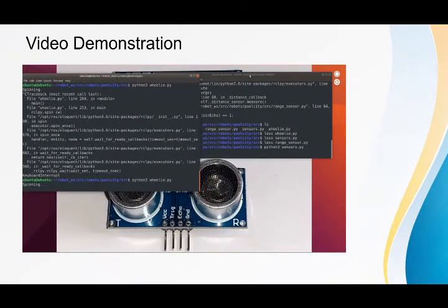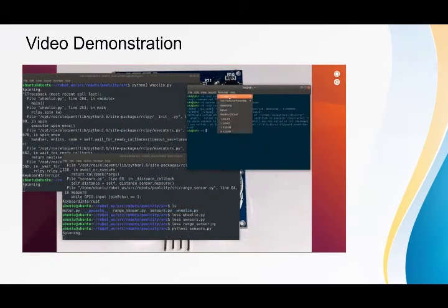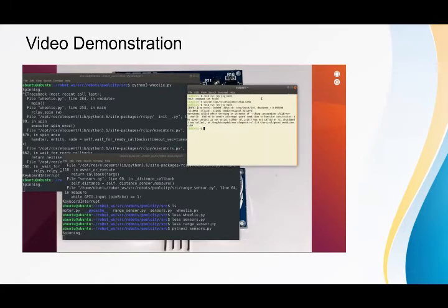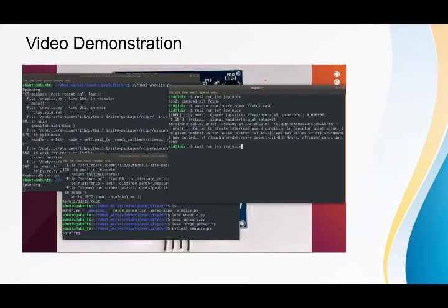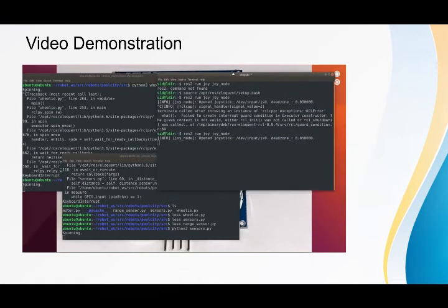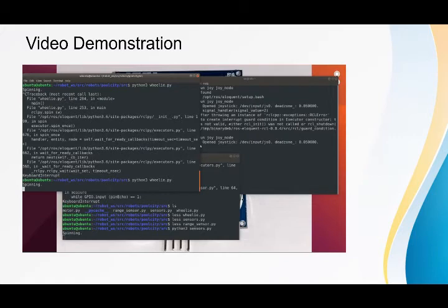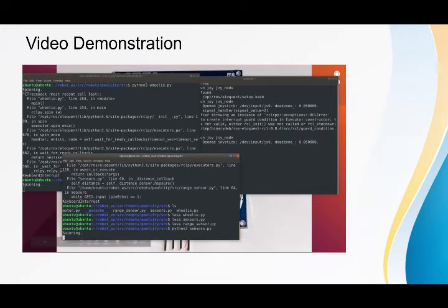The robot's going to be listening on that sensor topic to find out how far away it is, and then I'm going to run my Joy node once again on my laptop. Okay, so everything's all put together. I have 3 separate processes running. One on my laptop, that's where my joystick is connected to, and then 2 on my robot, one that's just for the robot sensor, and then one that controls the wheels.